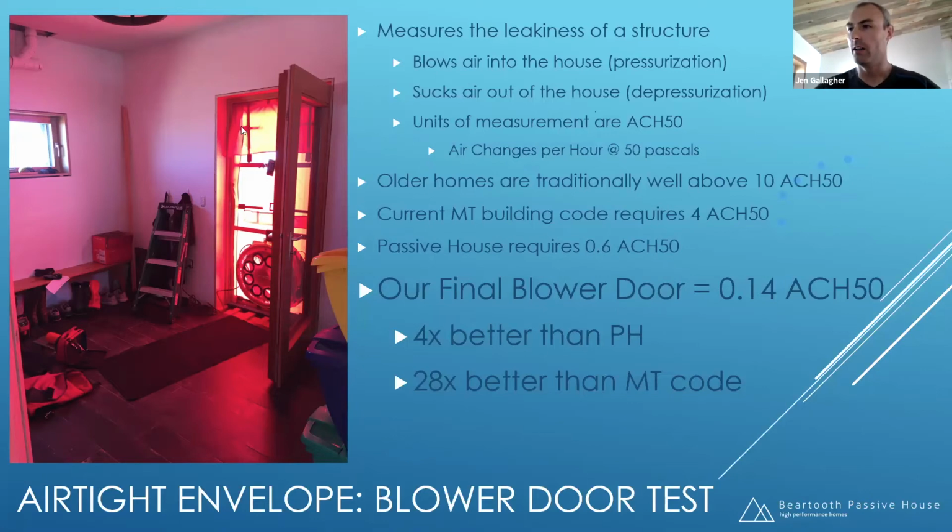And great numbers, but I was the one that did all of the install. I was the one that put the holes through the air barrier if they needed to be put through it. But it was just attention to detail in terms of when that was installed, to make sure that you think through the process of how do my ceilings attach to my walls, and how do I make that red line, when I draw it around my section of my structure, continuous? Okay, so that's the airtight principle. Any questions on that?